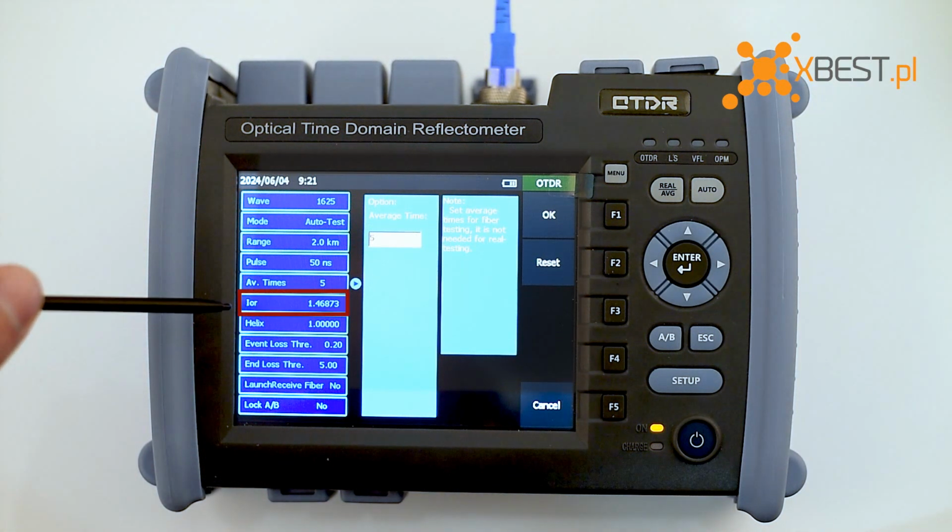The IOR converts the time that the OTDR measures to distance and displays it on the trace. Entering the appropriate value for the fiber under test will ensure accurate measurements of fiber length. To obtain accurate measurements, always clean connectors prior to OTDR testing.